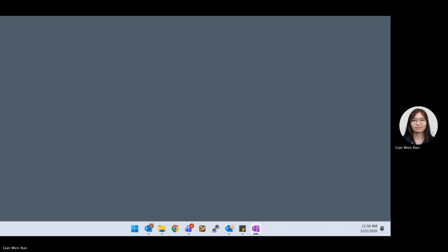We can say negative V out times RS divided by RD, and then you move here, so plus V in will be equal to your VS. So these two are the same thing. I just changed it a little bit to find VS. Now it looks like I can substitute everything inside. Let's first figure out what your VG is, because we know VGS is VG minus VS. We already got VS. And the VS here, it looks like we don't need to eliminate because it is just a resistor, and then V out, V in.